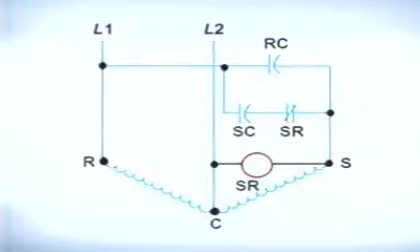When the motor is initially energized, both the starting and running capacitors are in the active circuit. Once the motor reaches its designed operating conditions, the starting capacitor is removed from the circuit, leaving the motor to operate as a PSC motor.